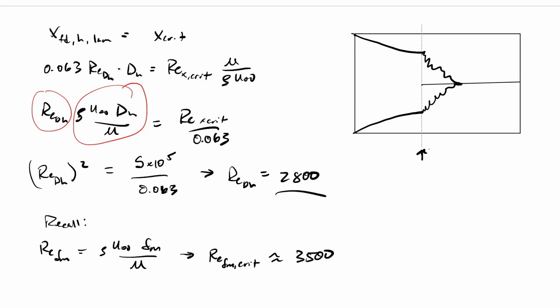Once you transition to turbulence, the boundary layers very quickly converge to the center line, because the turbulent viscosity, that is, how much do the turbulent eddies affect the velocity profile of fluid that's far away from them, becomes big. You have this big effective viscosity and a very fast boundary layer growth, and pretty quickly after you become turbulent, it converges to a single value. This is the center value there.